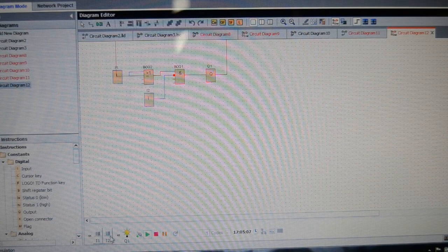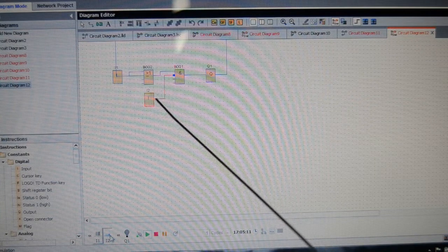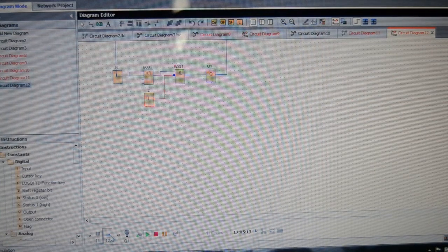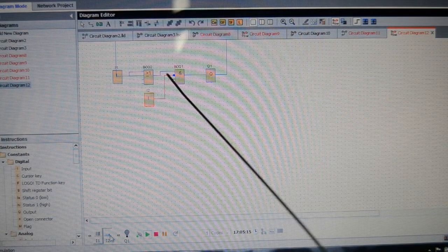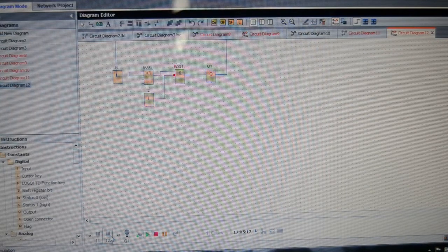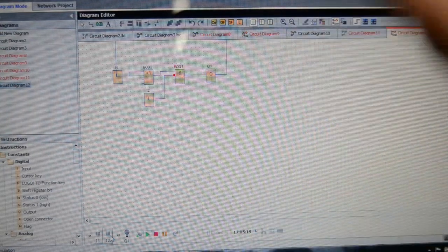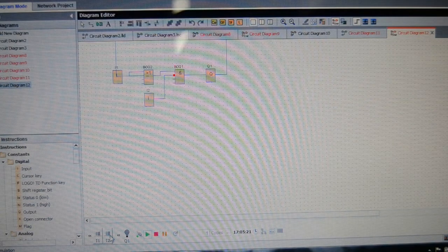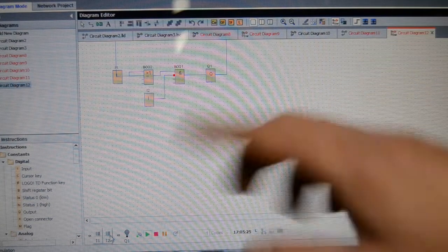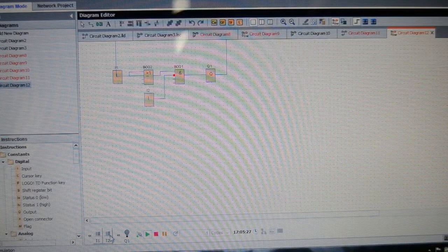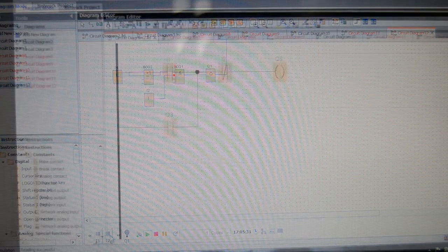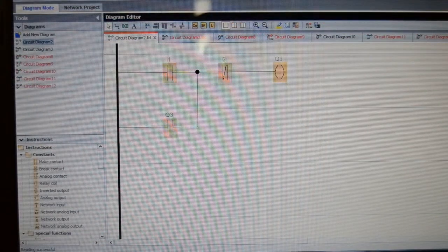When we then press I2, it becomes true, even though in actual fact it's false, and it's switched off the whole circuit. Can be a little confusing with the function blocks when you've got normally open and normally closed contacts, but once you run through the simulation, you can see what it's doing. It's relatively straightforward to understand exactly what's taking place. Right, let's look at a practical application.